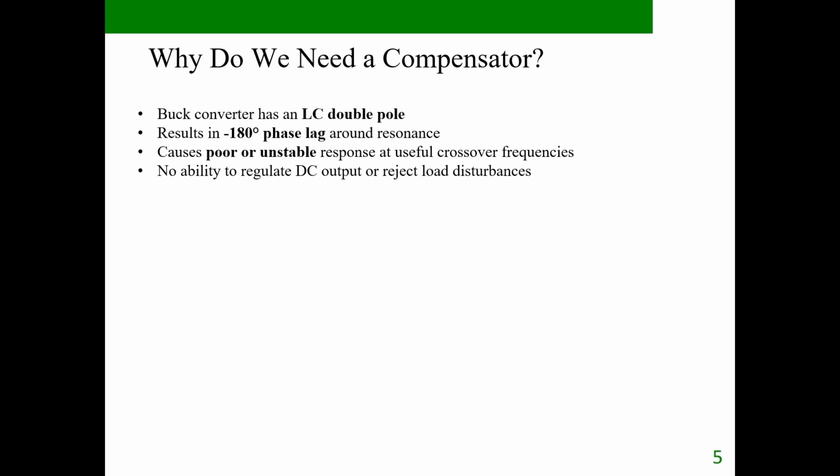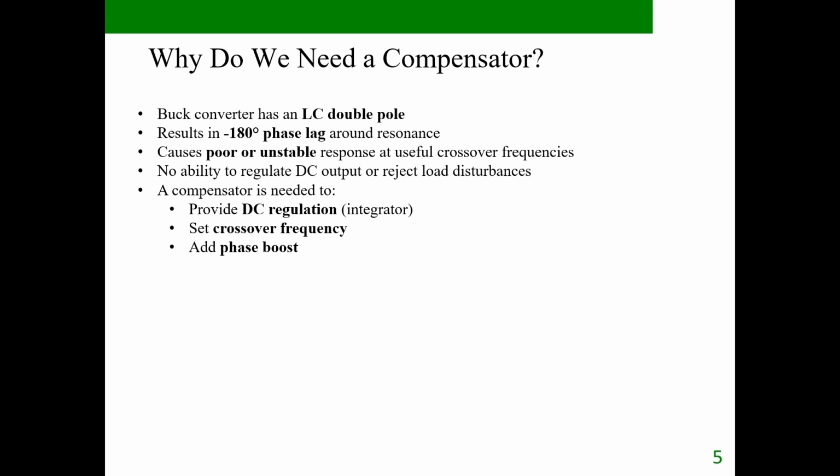A compensator is therefore required to provide DC regulation, shift the crossover frequency, boost the phase margin, and ensure good dynamic performance. This is why closed loop voltage mode control cannot work without a compensator.